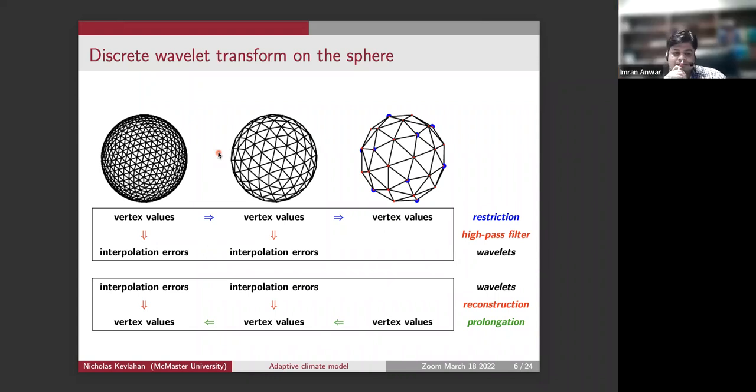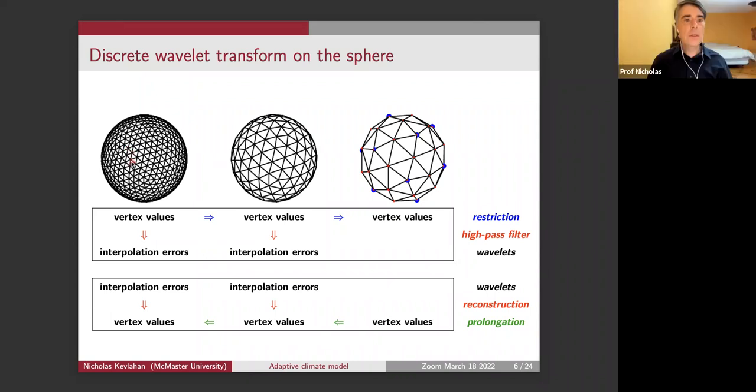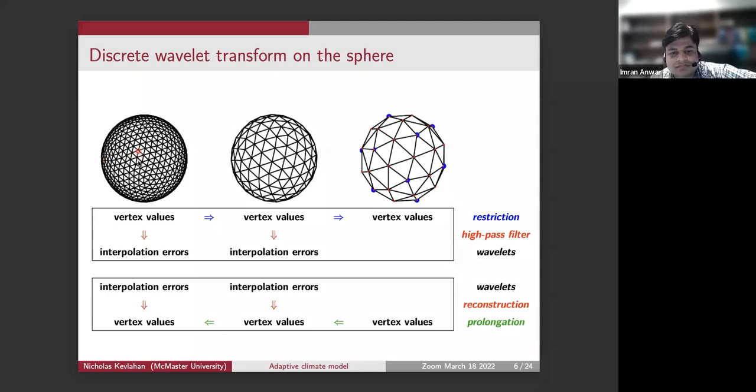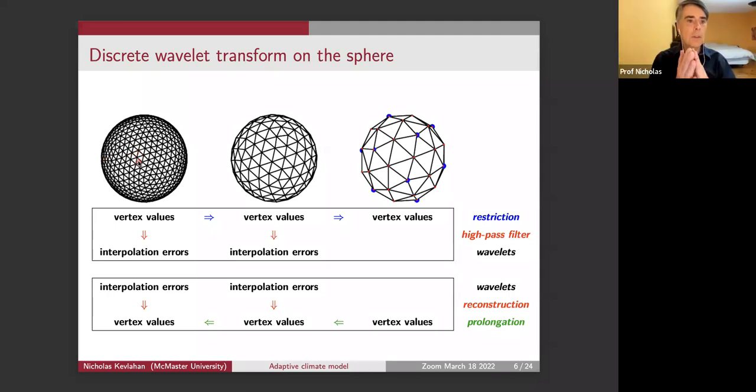And there's another problem too, is imagine that we kept refining because we want a very fine grid. The geometry of these triangles, there'll be certain triangles that will have very bad shapes. They'll be very acute, very kind of long and thin. And so one thing I'll explain later is you have to kind of fix that up. You have to move the grid around to improve the properties. So the basic idea is the same, but there's technical challenges.